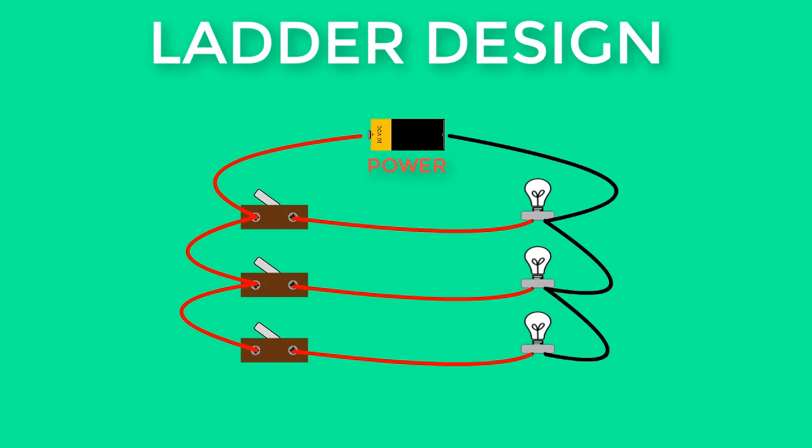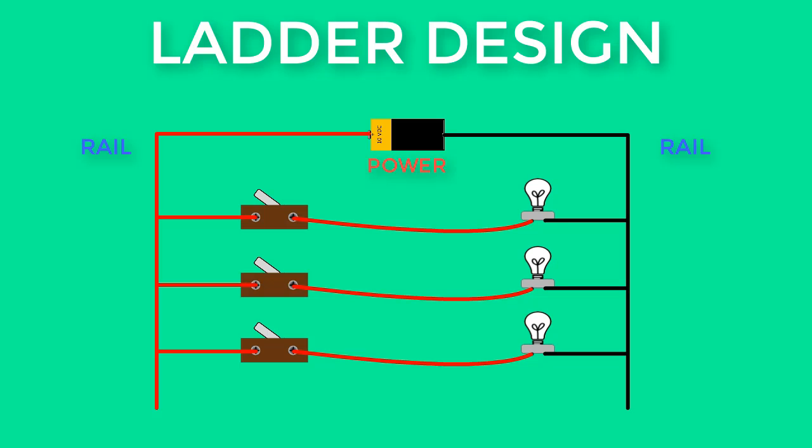Circuit diagrams drawn with horizontal components are called a ladder diagram since it resembles a ladder. The vertical drawing connections are called rails or power rails. The horizontal drawing connections between the rails are called rungs. A ladder diagram is a drawing that shows both power connections and the branch circuits connected to the power rails.